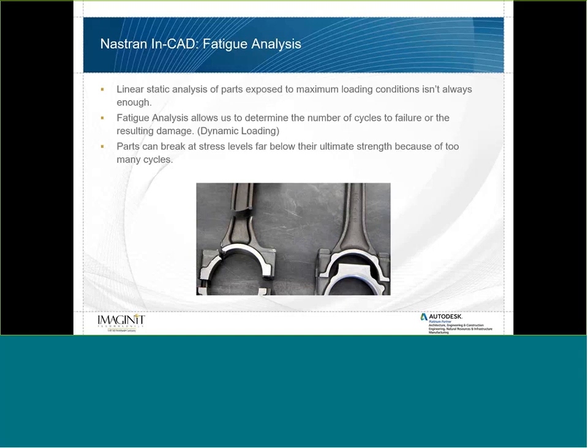There's a lot more things we need to consider with fatigue, but this gives us really some great insight into whether or not our part is actually going to break at a lower stress level than our maximum loading would suggest, due to the increased number of cycles and the constant wear that's caused by this type of dynamic movement. So there's a lot of good applications for this, and this is what we're going to focus on today.